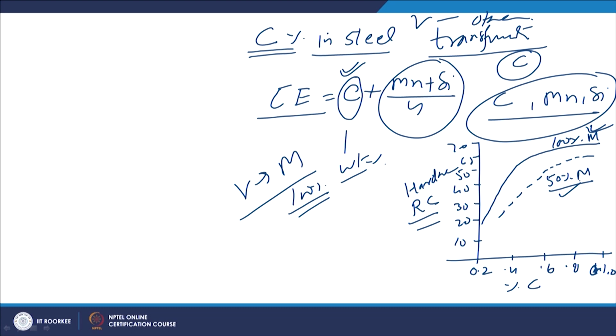So, despite having 100% martensitic transformation, low carbon steels may have lower hardness and so a reduced cracking tendency. When the carbon content of the steel is high, it forms 100% martensite of higher hardness. Whenever the hardness is high and martensite is being formed, this combination increases the cracking tendency and embrittlement of the steel.